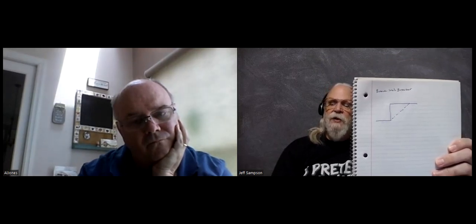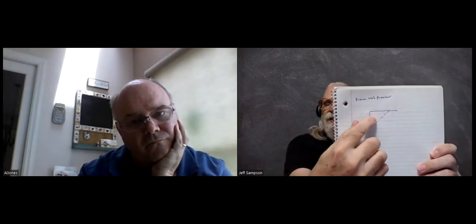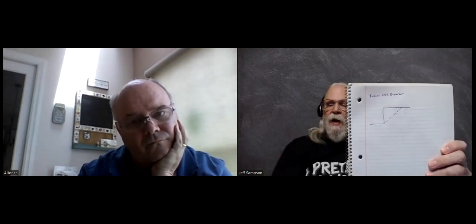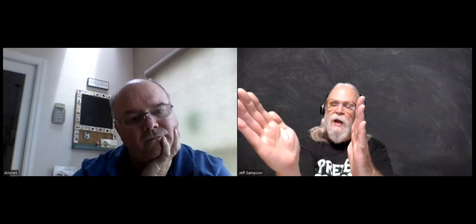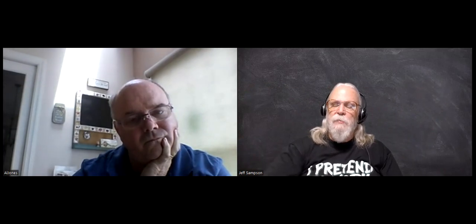Now, each point in here is a point in the loop as it goes through. If you're controlling, say, steering, and you're centered, and you go whammo, you go all the way out to the hard stop. Instead of doing that, you go click, click, click, click, click. So you're controlling how fast that moves out there. Since instead of going the full distance, you now just have a little distance each time, you can turn up the power on your PID also, because you're not trying to go the full distance. You're trying to go just a smaller distance as you go.